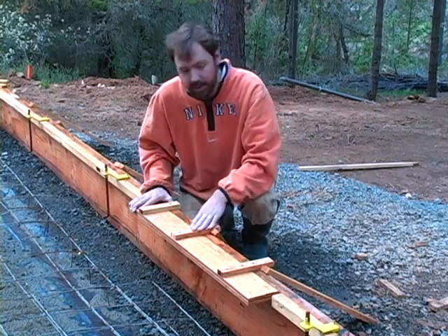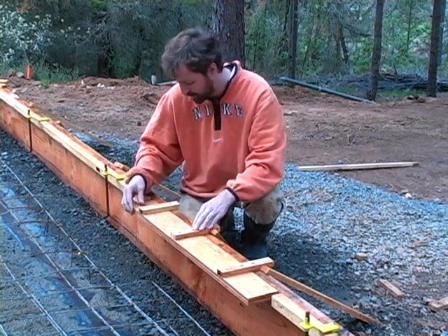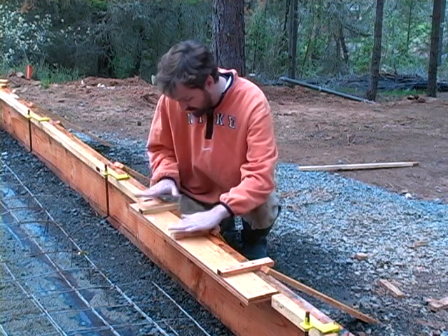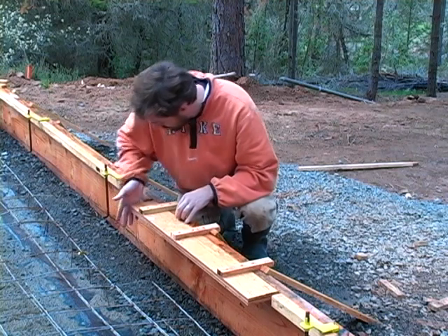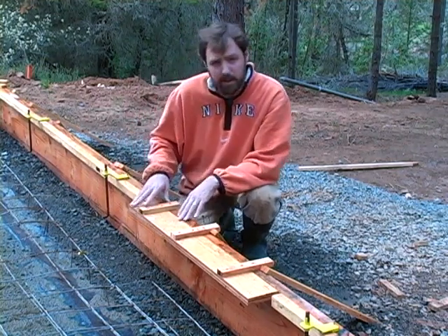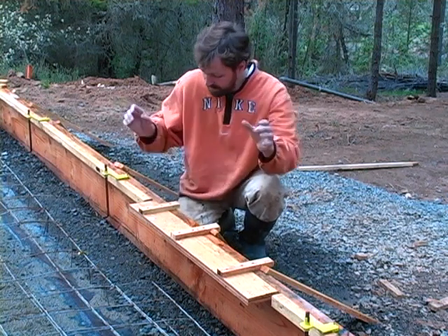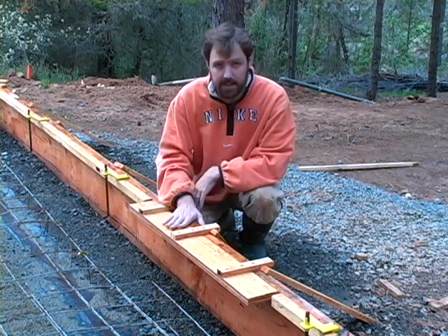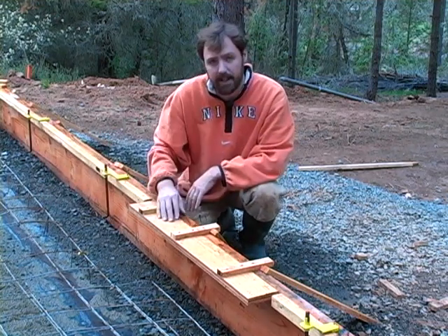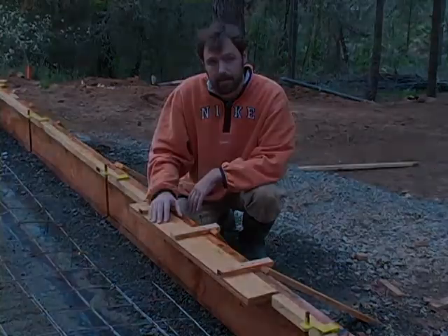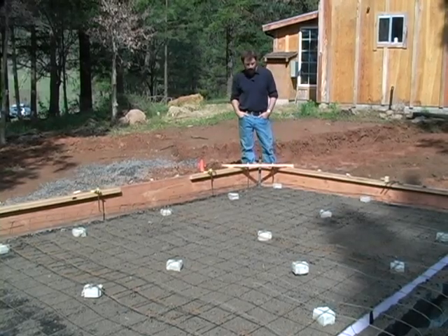I'm using another concrete cutout here. Basically what this is, is a 1-inch nominal thickness piece of wood, plywood, that is cantilevered out over the slab. Now what happens here is the concrete will fill up underneath this and around it, and when the concrete cures, this will end up being a notch out that's the exact width of the door threshold. So when we trim this out and bring plaster to it, this is a really nice detail which allows us to, once the concrete is cured, be able to sweep stuff right out of the house without having to deal with the threshold.